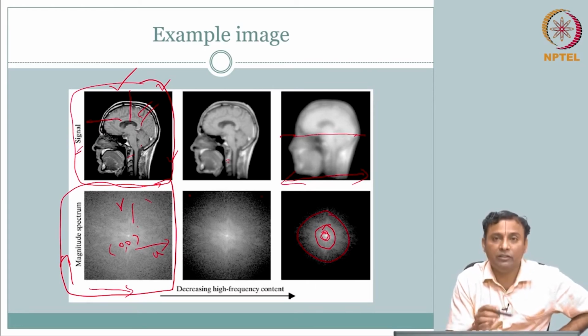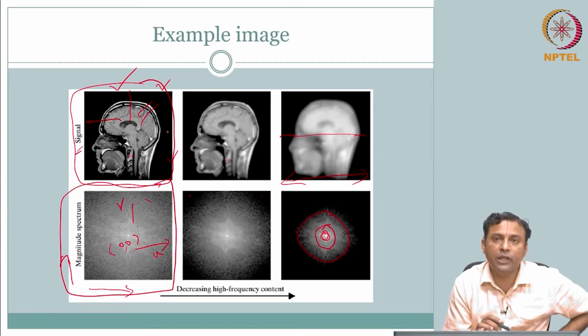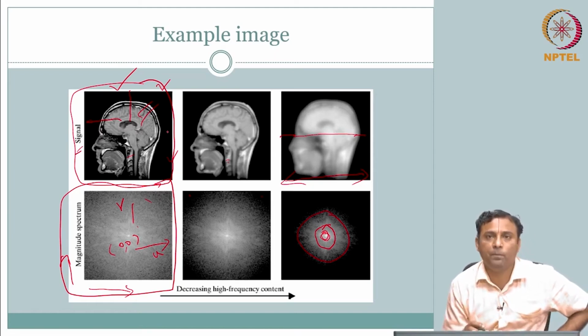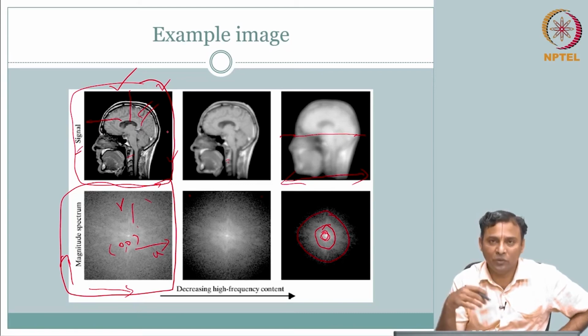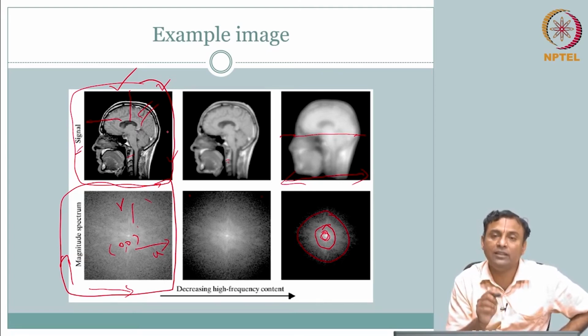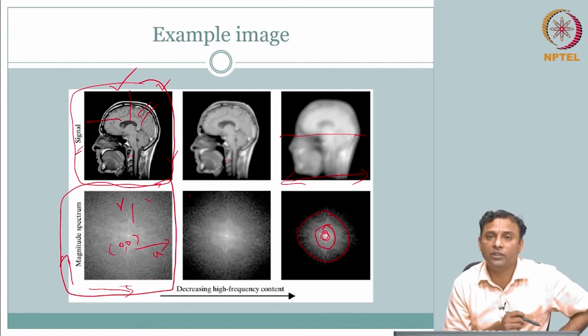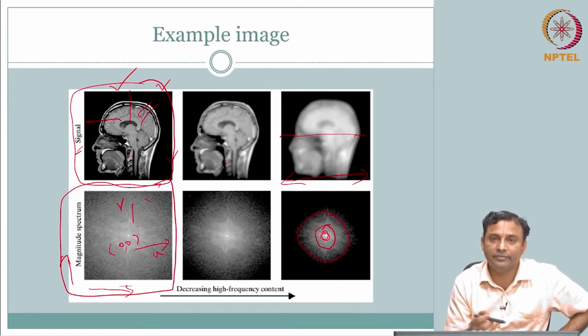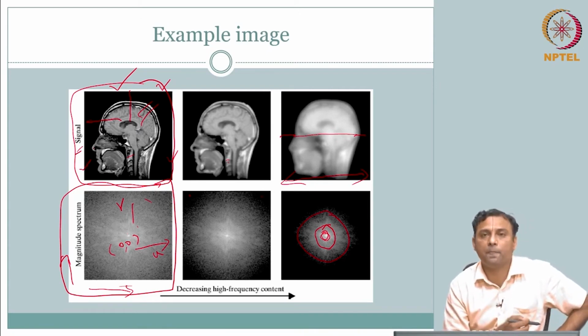So, the main point that I would like for you to appreciate here is, looking at this image, the length dimensions in the spatial domain, you can now perhaps eyeball and appreciate what we mean by spatial frequencies. In the time domain maybe we are trained, you could look at a waveform, count how many cycles there are and guess the frequency. So, here as well you should be able to visualize it, even though the 2D spectrum is not really going to have much pattern, it is going to have a DC and then high frequency content. The pattern will be visible here.